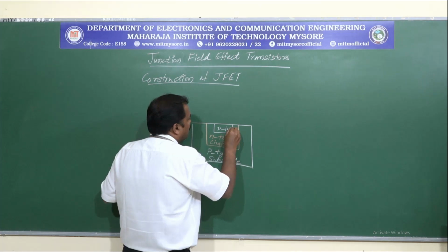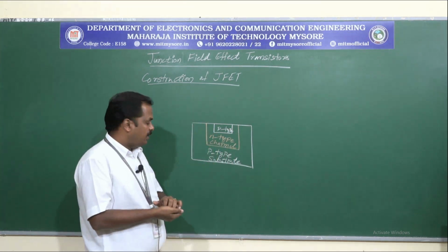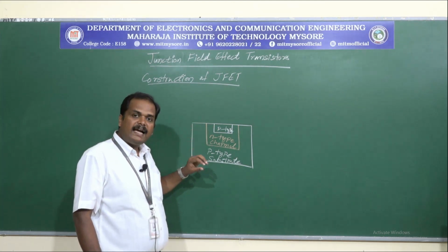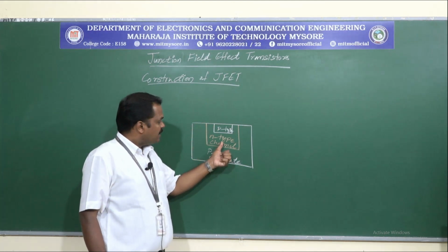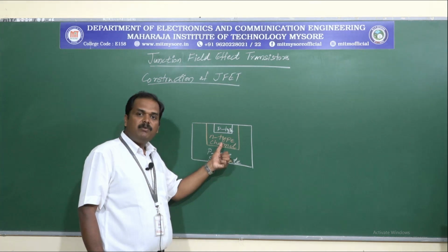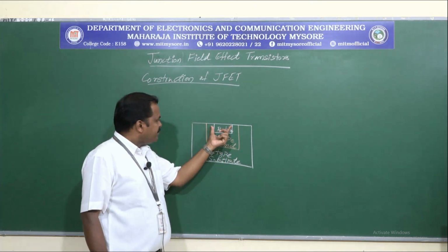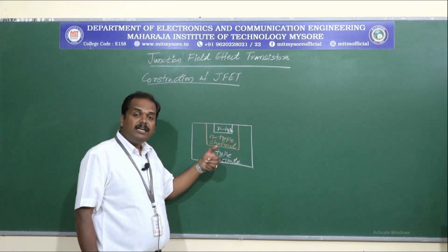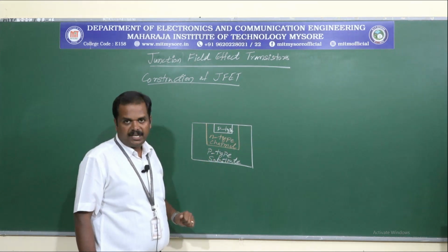This is P-type material. Now these two P-type materials will be working as gate regions, whereas this N-type material will be working as the channel, and these two ends of the N-type channel will be working as source and drain terminals.